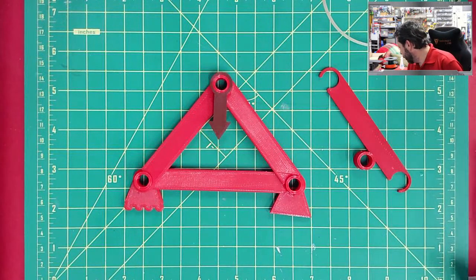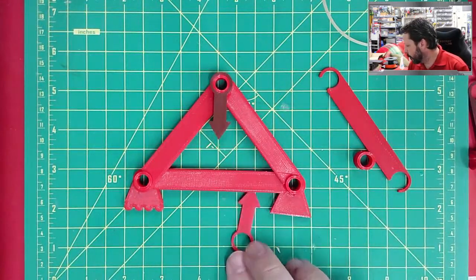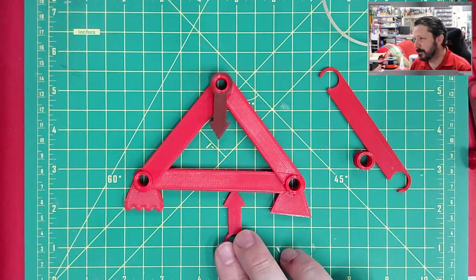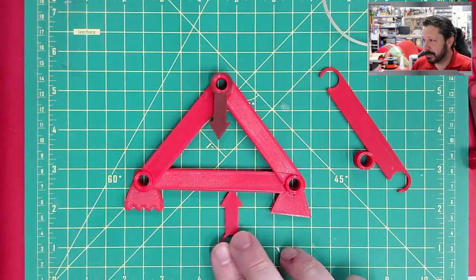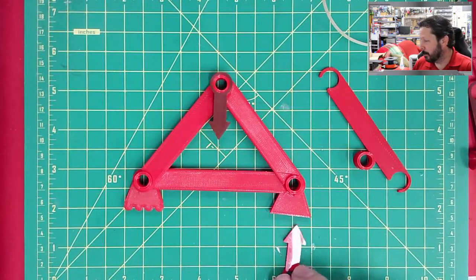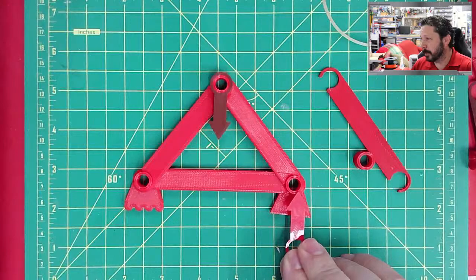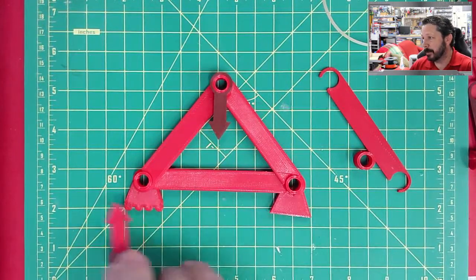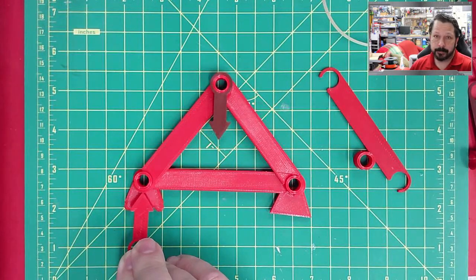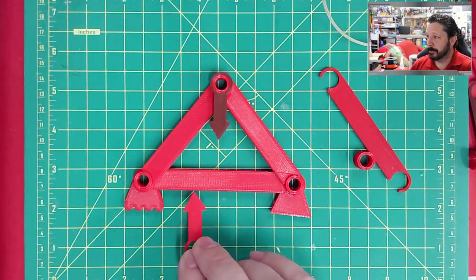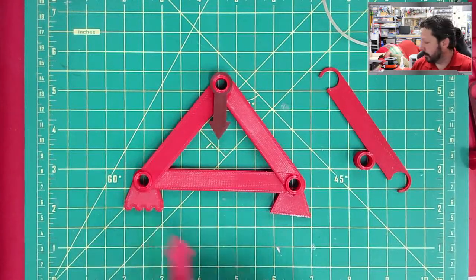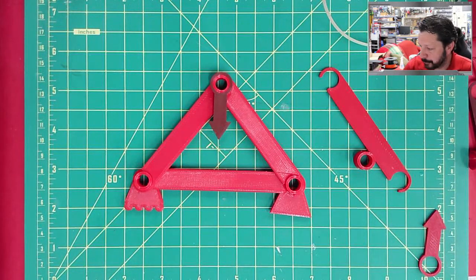So I wouldn't come in here and put a force on the joint itself. That turns it into a frame at that point, which we'll do frames later. But if I want to analyze it like a truss, then this force has to be taken into account by putting it at a joint somewhere, or maybe dividing it up and putting part of it here and part of it at this joint. So I can't put the force directly on the member anywhere. I have to put it only at the joints if I want to analyze it as a truss, which is what we're doing right now.